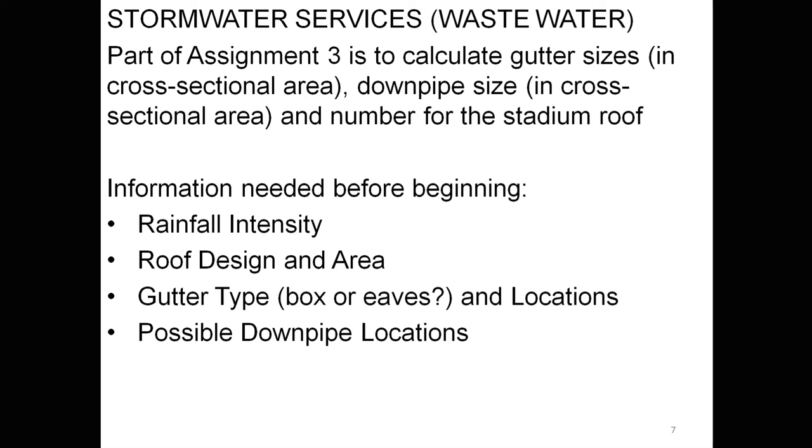But we won't be looking at that. We really just want to know how it's going to get off the roof without just falling off the edge of the roof. Okay, so I suppose what I'm saying here is you do need to look at your designs to make sure that you know where all the low points are. There may be points in your design where water decides to pool. That's absolutely fine. There's no issue with pooling water on the roof. We just have to design a way to get rid of the water from that pool.